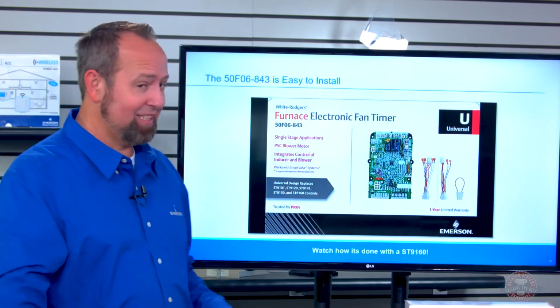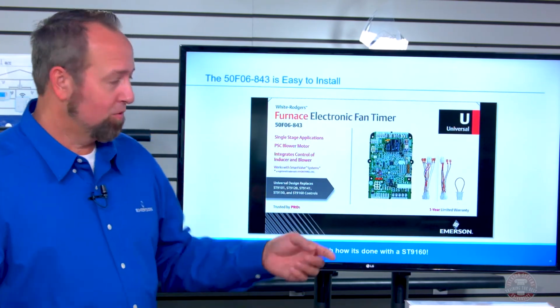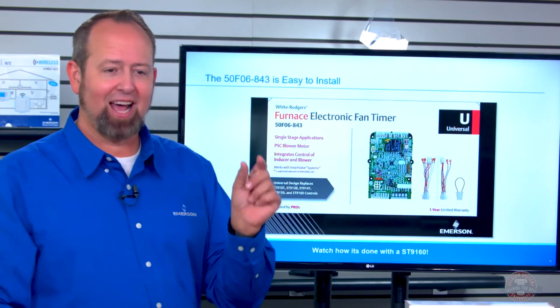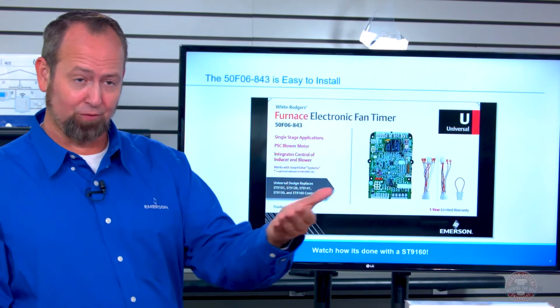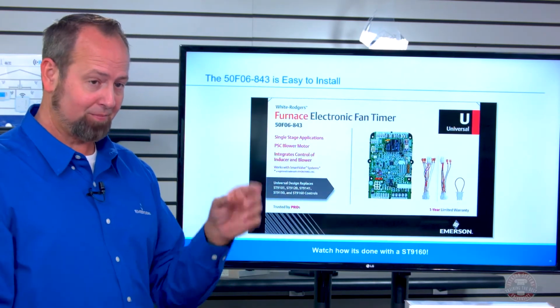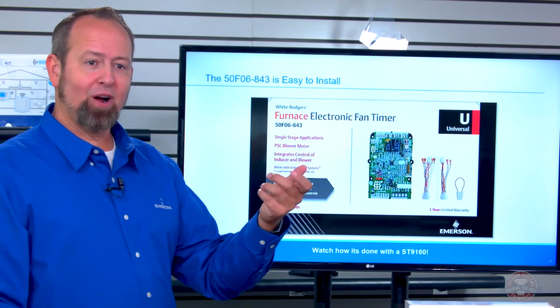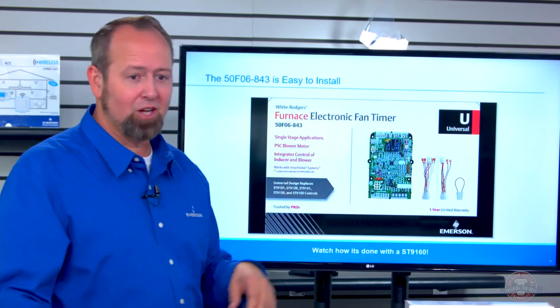The other two, the ST9141, would take one of these adapters, and the adapter itself has a tag on it that says ST9141. So if you're pulling out an old control, you see the model number on that control, you pull out the wiring harness that has the matching number on it, and you're good to go.